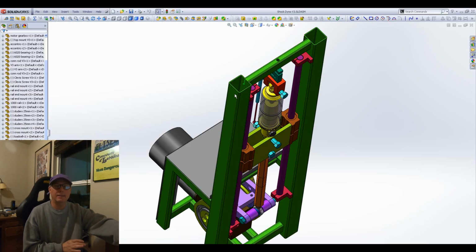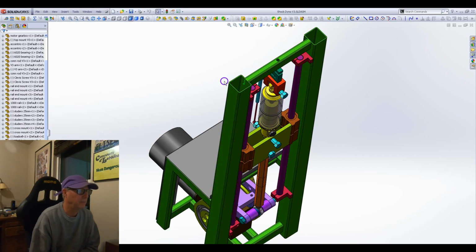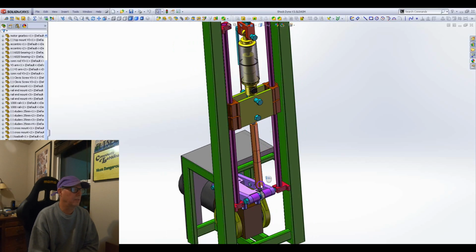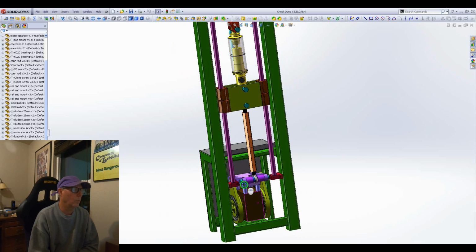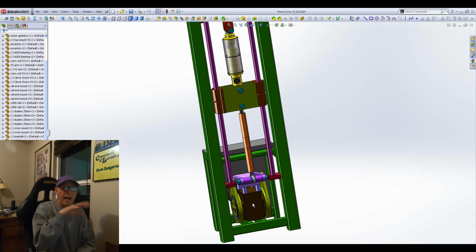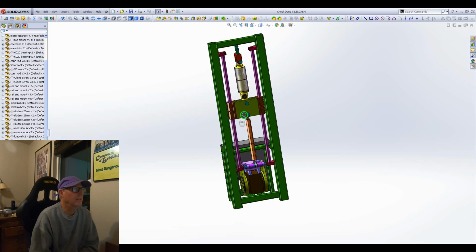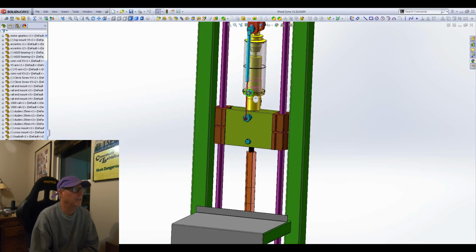So anyway, I made this less stiff, knowingly. This is steel, but still less stiff. But instead of just knowing the position of the actuator, whether it's a linear actuator or a crank, or what most people in the industry use, a Scotch yoke, so you get pure sinusoidal motion, what I've done is put a linear transducer on here.